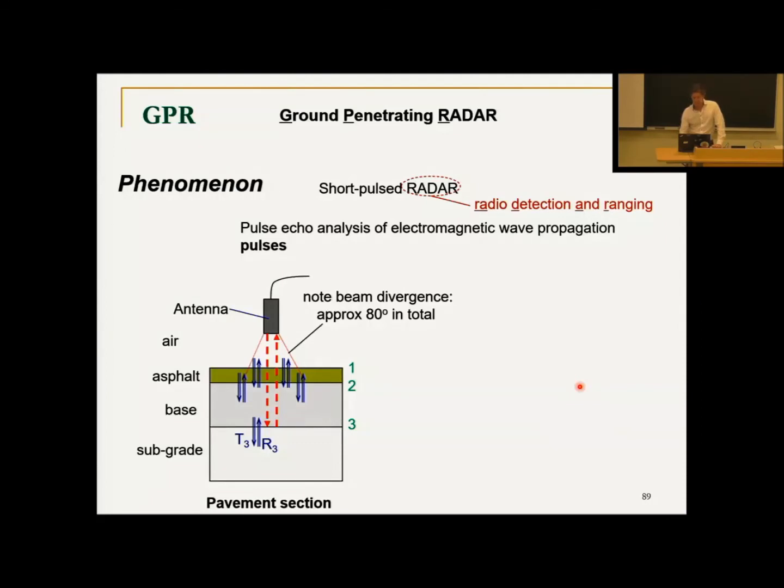In radar, which is sending an electromagnetic pulse and then being quiet and listening, just like an ultrasound, we emit the pulse and we look for reflections. Because of the good transmission between air and solids, we can have a contactless injection of the energy, because a lot of the energy goes through, relatively little is reflected back, and this can penetrate into materials and we can look for reflections at interfaces.